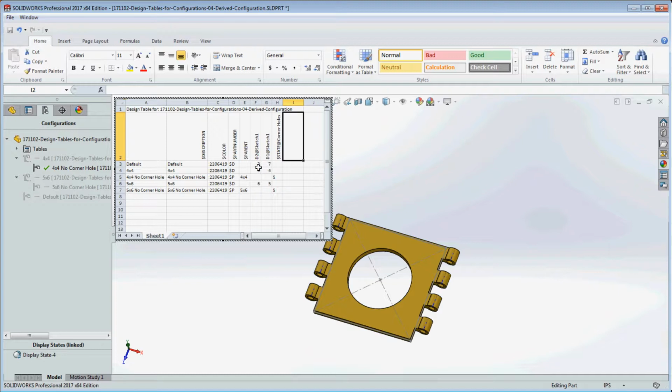These are the values that can be changed. So if you remember, default values over here is going to be 3 inches in that dimension over here, and then 7 in the back. So it's got those dimensions in here. And if you look at this, the way this is described, it's D2 for dimension 2 at sketch number 1. So our sketch number 1 in our feature manager over here is going to have 2 dimensions.